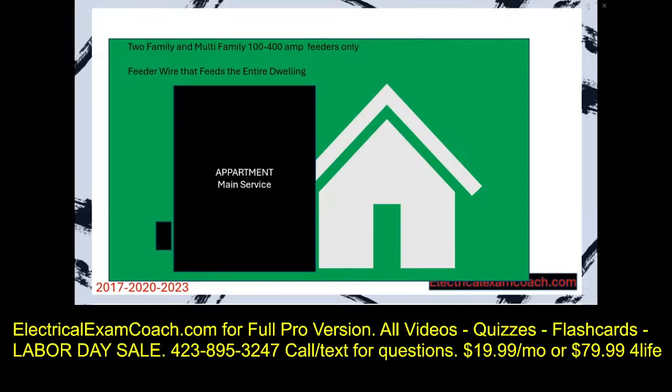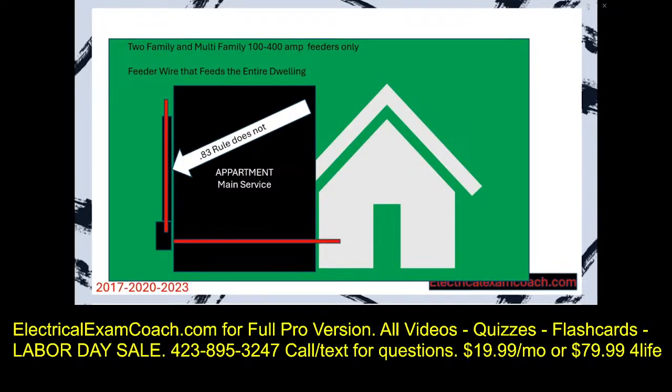Let's imagine that you have your meter center out here, you have your service riser, and then you have your wire going up. That wire there, the 83% rule does not apply. You're going to use all of the previous rules that we learned before and apply those. But the individual feeder going into that unit does. The 83% rule does apply.